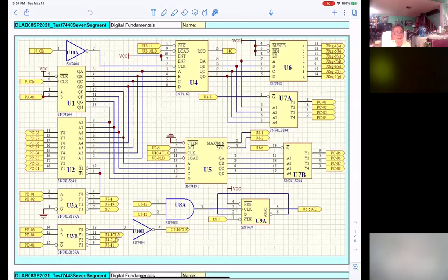That's a BCD counter. This counter can, first of all, be cleared. The clear is active low. That means pin 1 at 0 makes the output 0. If you don't know, you can look back at the timing diagram for the U4.